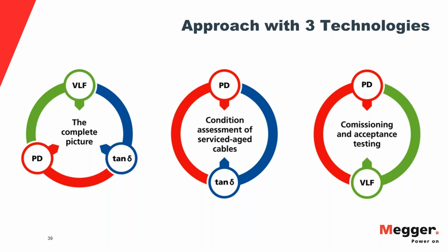Okay? We run into the same spirit of the same question in fault locating. The first step of fault locating is to do a DC hipot, but I try to avoid using those words. I try to say DC breakdown test because, exactly as we've been talking about, the duration is kept very, very short, really 15 or maybe 30 seconds. So there's also a time component in there before these trapped space charges become a problem.